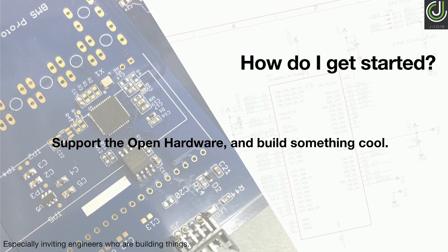So there's really 2 parts to that. The first part is that the instruction width is fixed at 16 bits, and so suddenly you have half the memory bandwidth there. But that's not the end of it. Instead of that simply being a compressed instruction set like the RISC-V C extension, those instructions actually represent constructs that the compiler will emit.